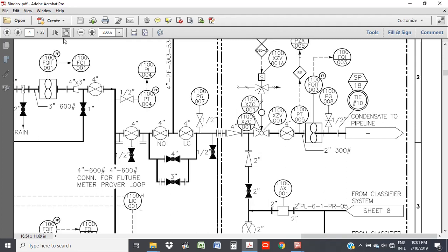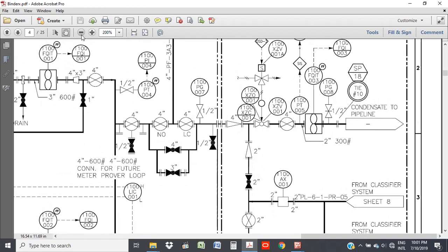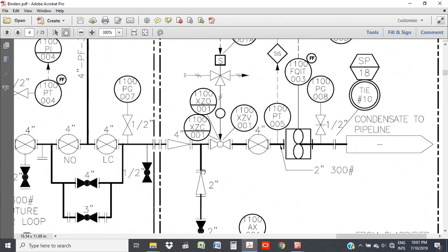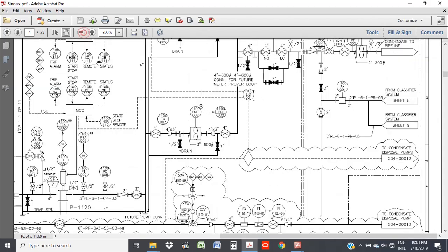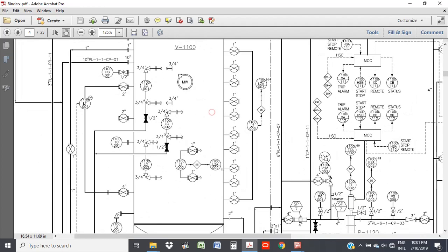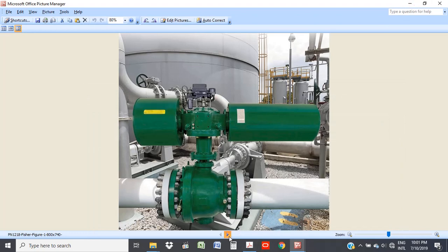You also use them for process offsets. You put a shutdown valve there. For whatever reason, if there's a process offset, you have alarms going off, and this could actually stop that by stopping the flow, and okay, the whole plant has been shut down. You could have a unit shutdown, which is just around an equipment, or you could have a total plant-wide shutdown, which would be the entire facility shutting down. So yep, that's it on this.